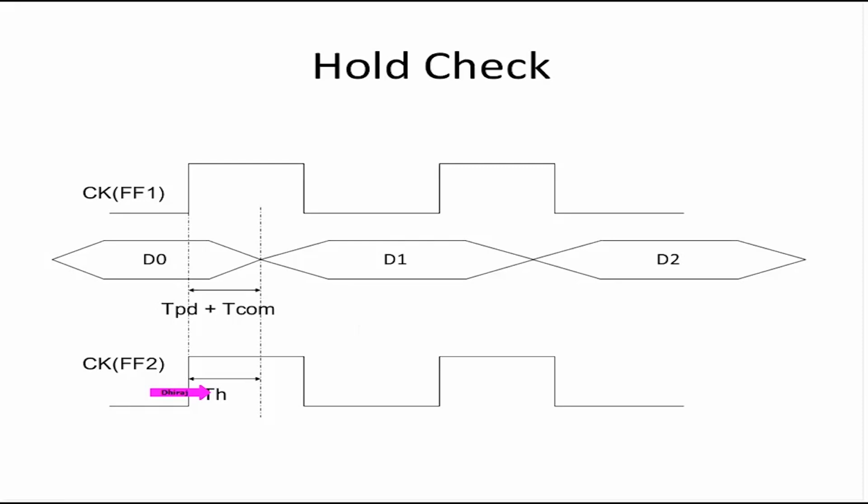So this is where the clock skew is very important. In post layout data, PrimeTime calculates the clock latency for every clock and it knows the clock skew between every pair. It doesn't calculate clock skew separately, but since it knows latency at every point, in the timing report you can see the clock skew. So this is why clock skew is very important. We will see how we estimate clock skew in pre layout, and how we handle clock skew in post layout.